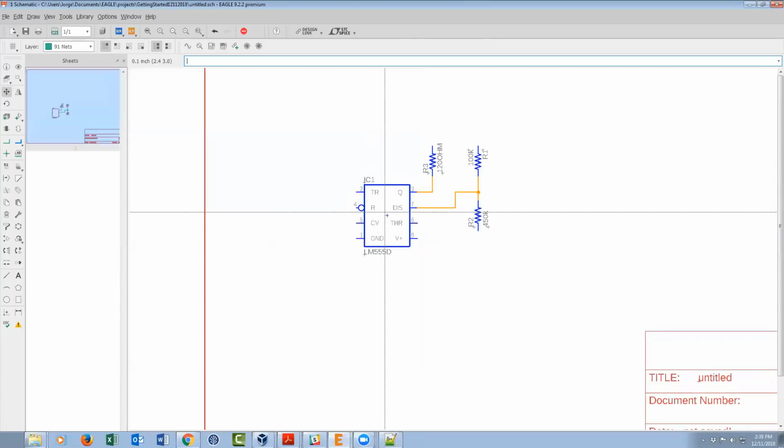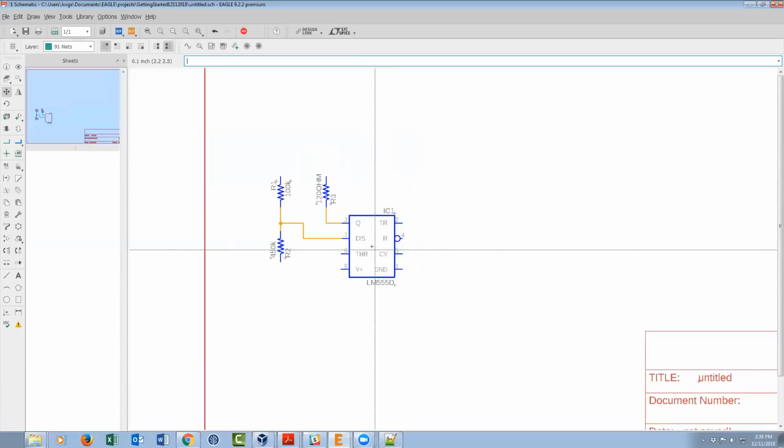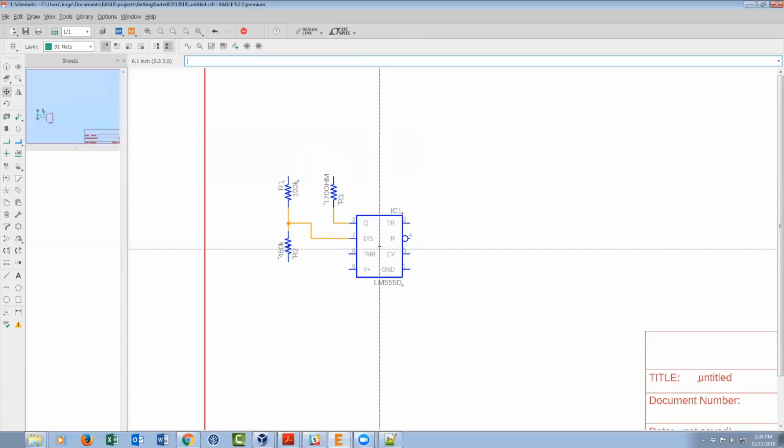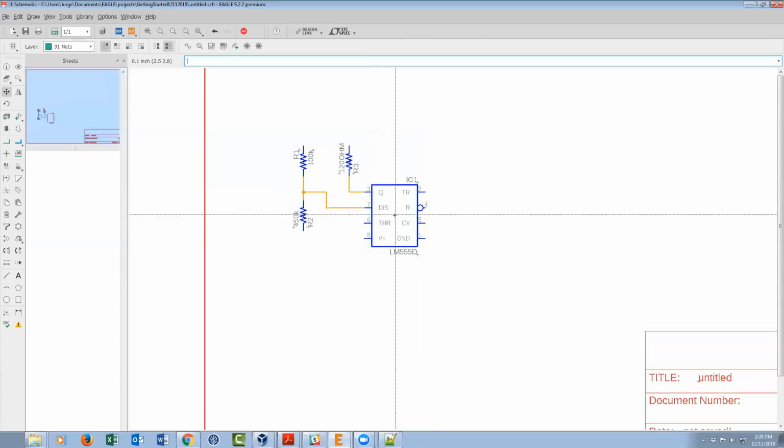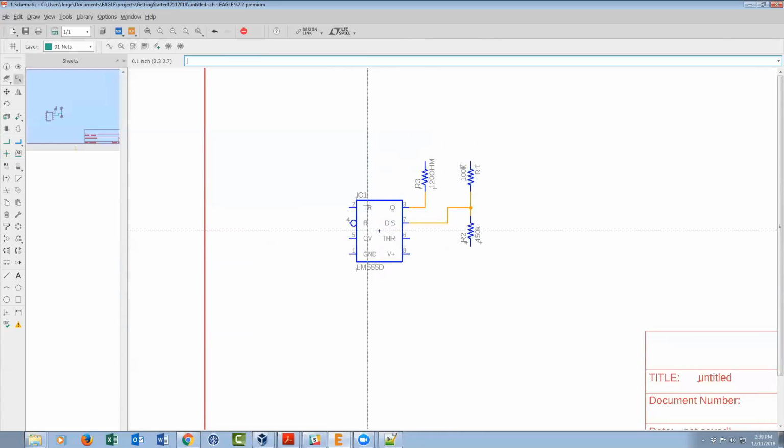Okay. If you have a scroll wheel, which we highly recommend working with a mouse that has a scroll wheel, you can click it like a button, and it'll mirror, as you can see. Okay. Now, in the schematic, it'll do a mirror like you expect, basically the mirror image. On the board, mirror carries a different meaning, so we'll be talking about that once we get to the board. So I'll put that there.